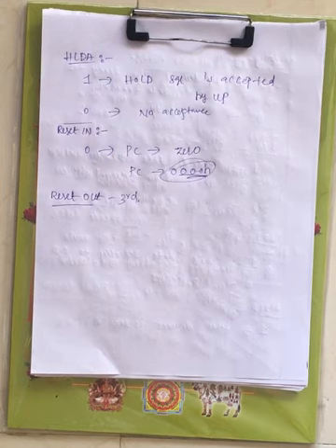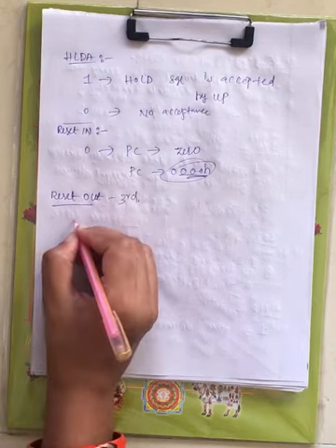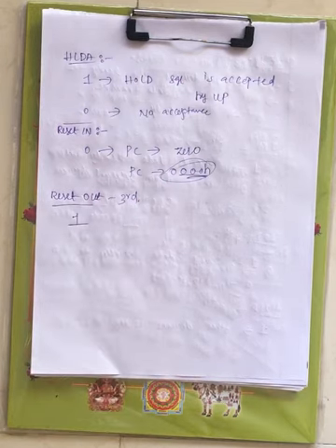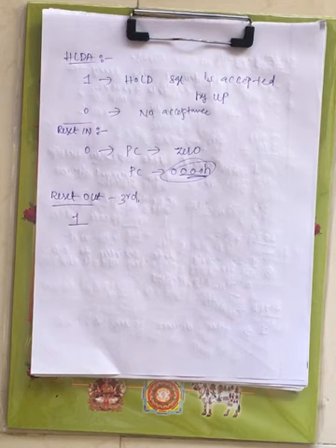Once the processor is reset, all the connected devices must also be reset. This is done for active high. When it is 1, the microprocessor will get reset, and whatever devices are connected to that microprocessor will also get reset.